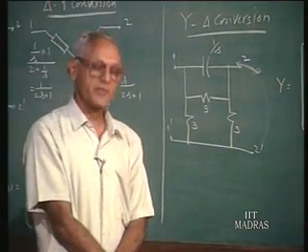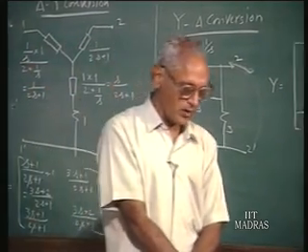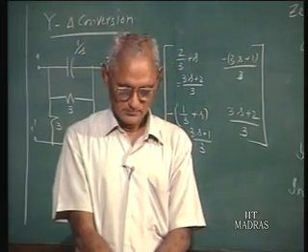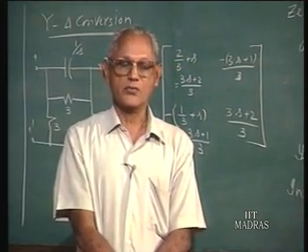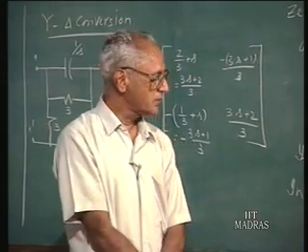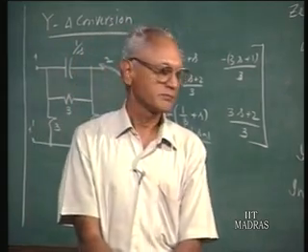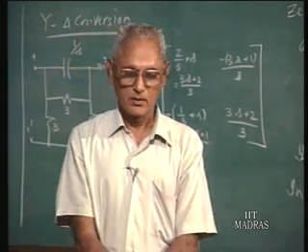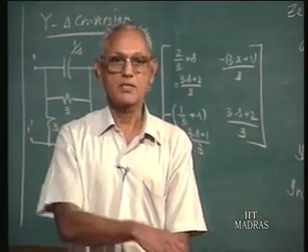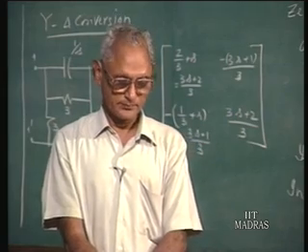A word about this zero of transmission or zeros of transfer function. We know that the poles and zeros of driving point functions have certain restrictions as far as their natural response is concerned. From the point of view of stability of a passive network, we already observed that the poles and zeros of passive driving point functions must be in the left half plane, and if they are on the imaginary axis, they should be simple.